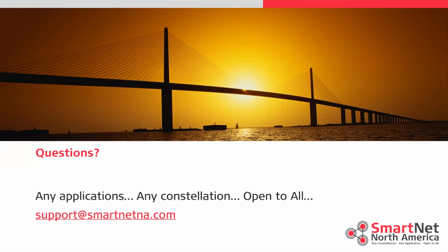You said you're switching to the 2014 reference frame as a reference frame that NGS is. Okay, so this goes back to ITRF 2014. It's in the back end. That's our physical coordinates, our processing coordinates. Updating those does nothing to affect you, except that it improves the network corrections overall. The broadcast coordinates, when we change those, those are what affect you.